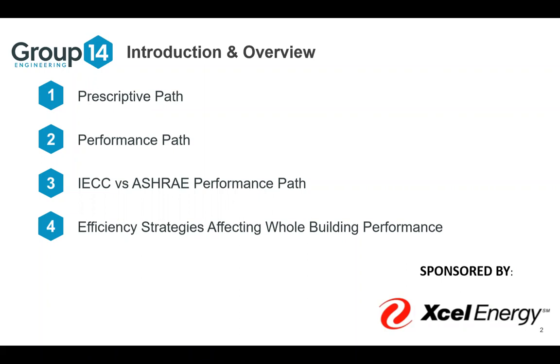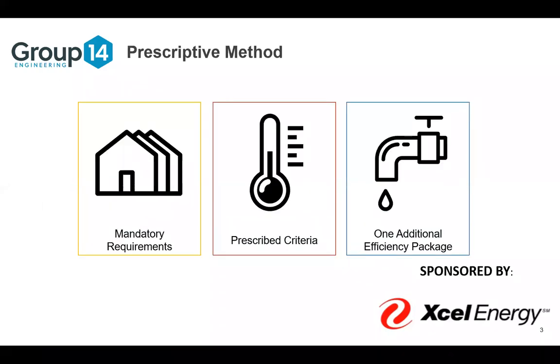I also wanted to note that this is all for the 2015 IECC. I have a couple notes in here for how the 2018 IECC changes, but the majority of everything we're going to be talking about is the 2015 IECC, or ASHRAE 90.1 2013, its friendly cousin. As you all know, for the prescriptive method, you have 3 things you have to meet within the code: all the mandatory requirements listed in the IECC, the prescribed criteria, and then 1 additional energy efficiency package located in section C406.